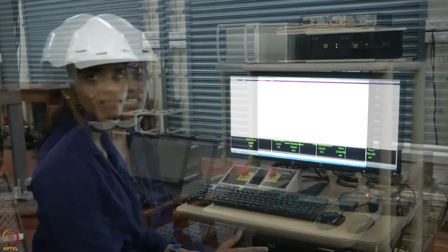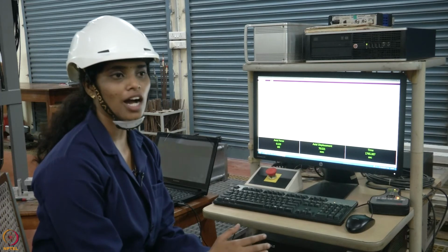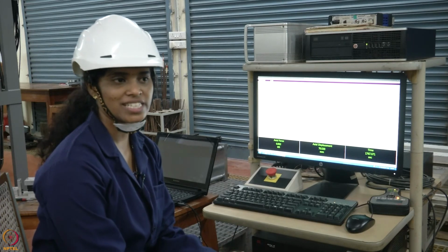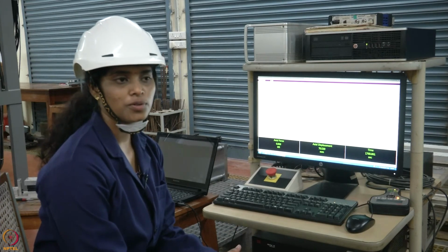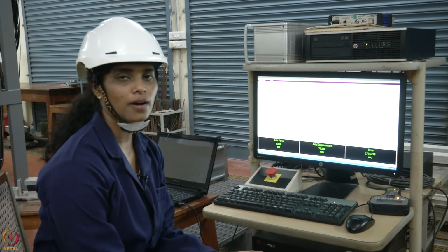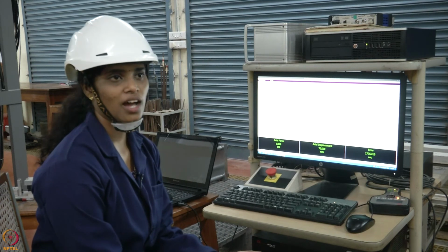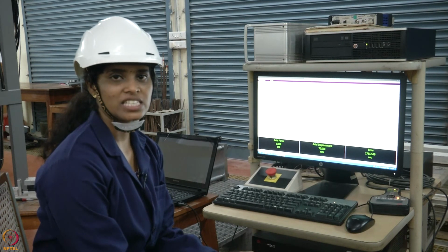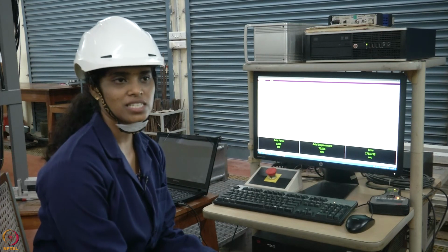In this section we have learned how to do a tension test for the pre-stressing strand, how you need to prepare the strand specimens, the test procedure for the tension test, and the procedure for obtaining the stress-strain behavior of the pre-stressing strand.